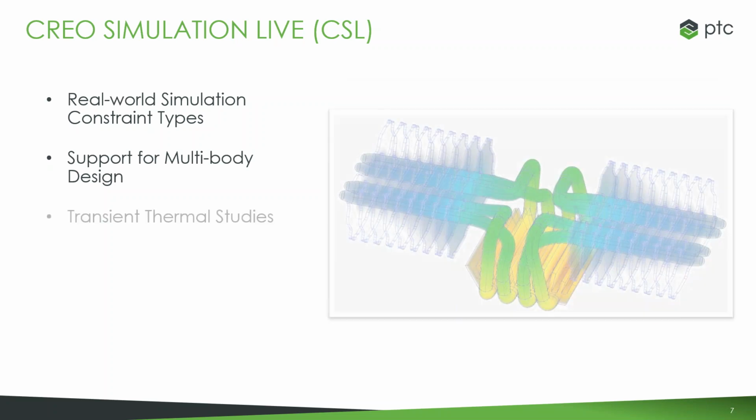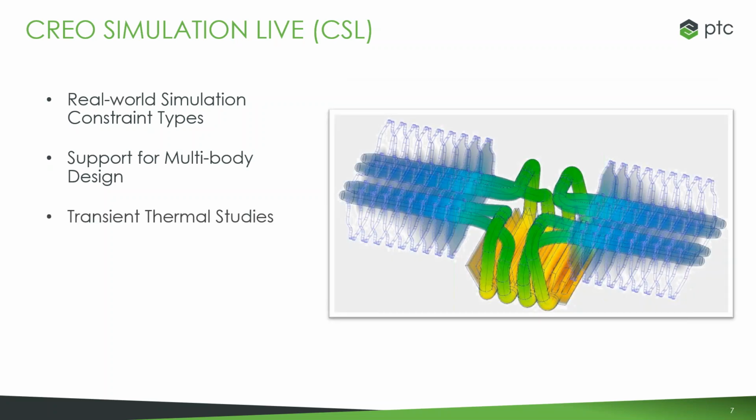And specific to thermal studies in CSL, you can now do transient studies, aka time-dependent analysis. So it allows you to see how your results are changing over the course of time. So you can do either the steady state or the time-dependent with that transient study.